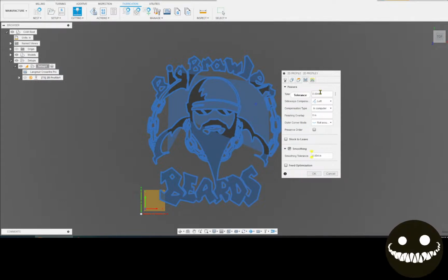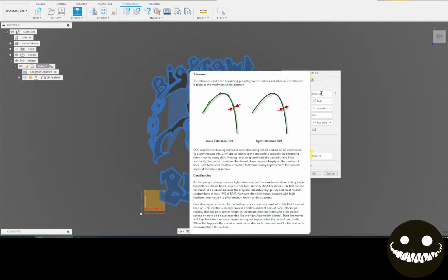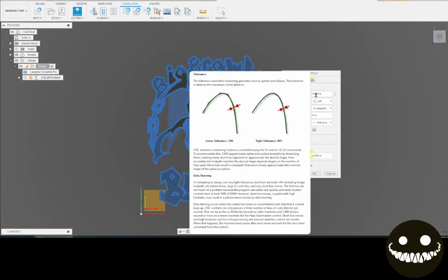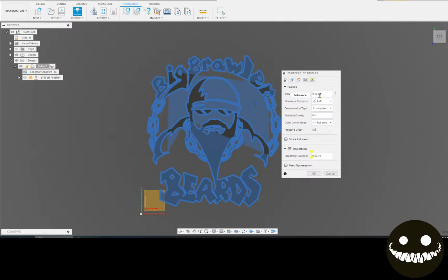And the reason we do this is a couple reasons. Data saving. It's going to vastly reduce the amount of lines of G-code, which is both going to help develop the tool, and it's going to be nicer on every part of the operation after this for running it. So that's probably the more important reason for running this. We could develop a toolpath with and without doing it. You can see how many lines different of G-code is involved. But anyhow, that looks good.